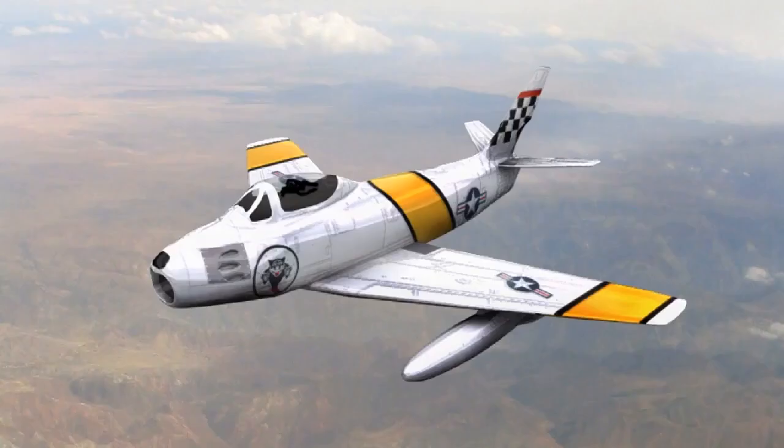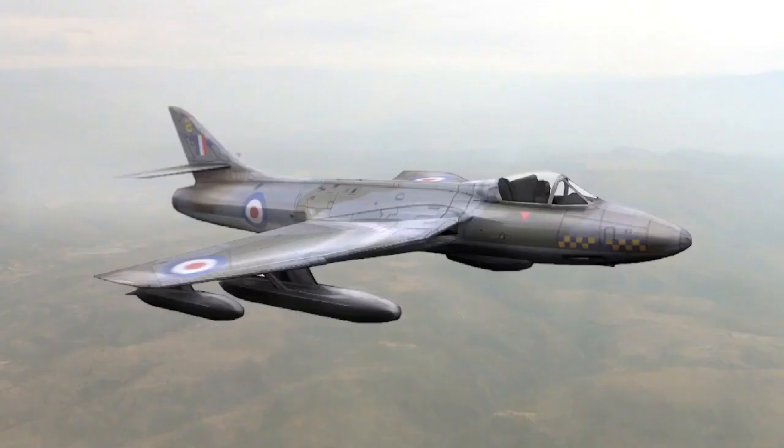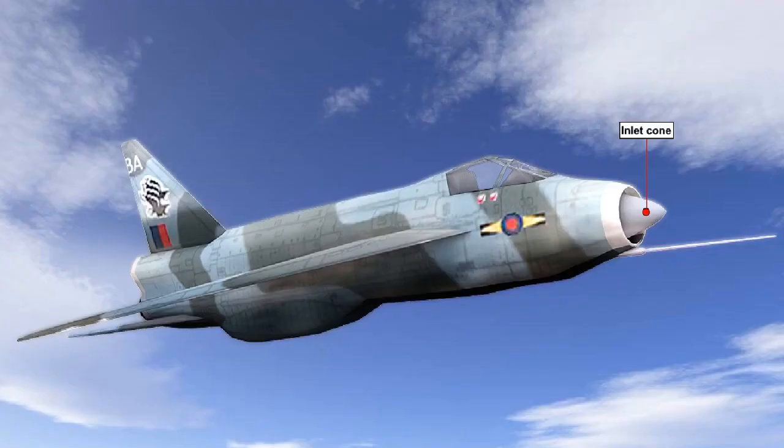The supersonic diffuser can be quite simple or quite complex, depending on a number of factors, among which is included the supersonic speed range of the aircraft. For instance, many jet fighters are not designed for sustained supersonic flight, and can therefore use quite a simple intake diffuser. Some of the earliest types of supersonic aircraft featured a central shock cone, called an inlet cone, which was used to form the shock wave. This form of shock cone can be seen here on the English Electric Lightning.